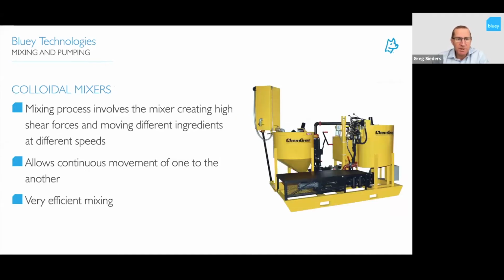Then you move to your colloidal and your high shear batch mixers. The mixing process for the colloidal mixers is creating high shear forces and moving different ingredients at different speeds. These are very efficient mixers and designed for your high performance PT grouts and high flowable grouts. They mix very quickly and very efficiently.